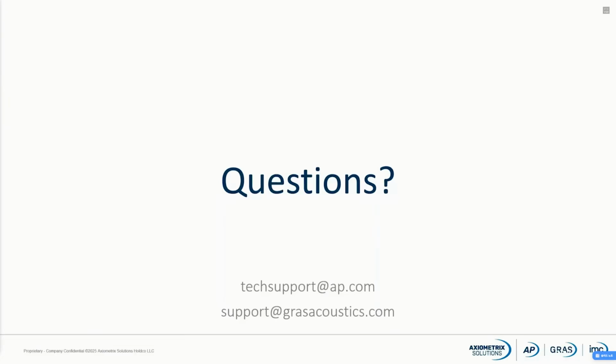So we have some questions already. Someone has asked, how is the value of 10 millivolts per Pascal determined? In APX, our default value is 10 millivolts per Pascal, so I was just using our default. The microphones I'm using were, I think, 9.5 or something like that, so it was close enough for me to demonstrate how the measurements work. But for your own sensitivity, you would obviously check the data sheet for the microphones that you're using.